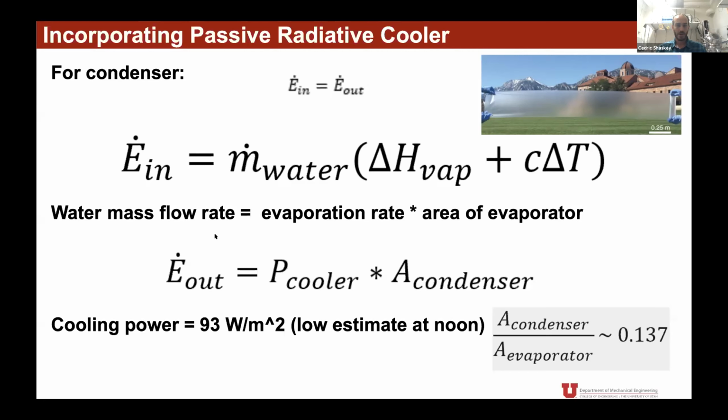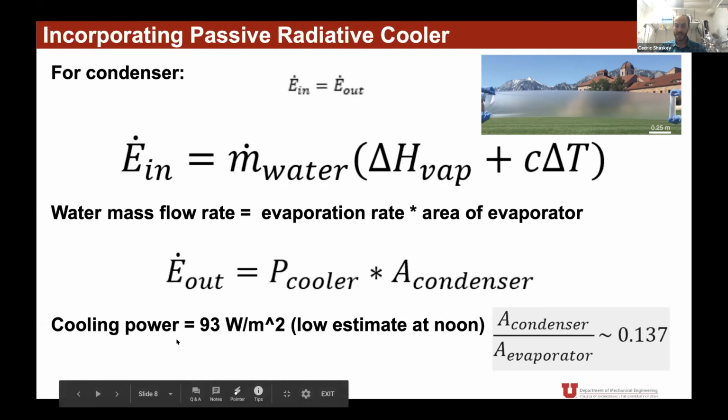And so we want to apply this onto the condenser surface and also the freshwater basin. As I mentioned before, we want to have that freshwater basin at a lower temperature than the saltwater basin. That's because freshwater evaporates at a lower temperature than the saltwater, so we don't want to have any back evaporation. So that's where this delta T comes in. We want that to be about 10 degrees Celsius.